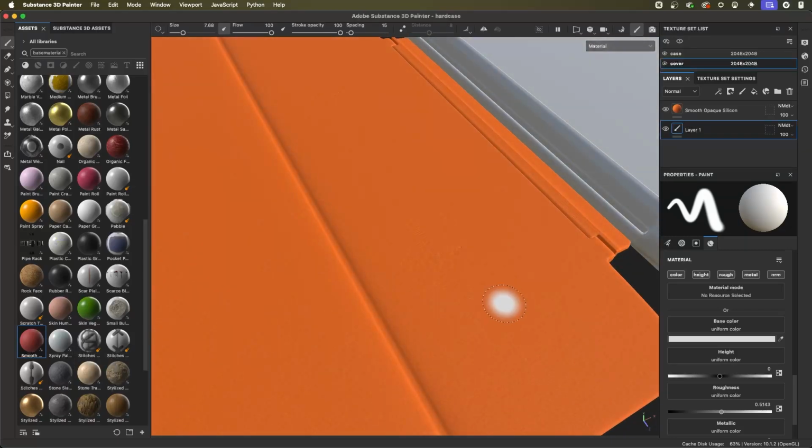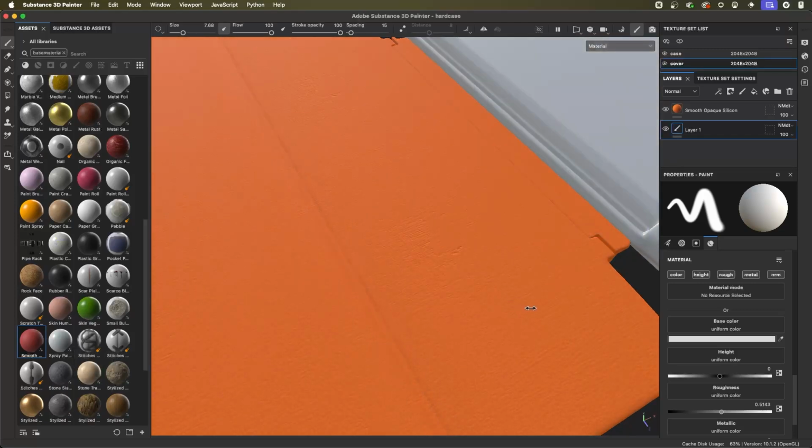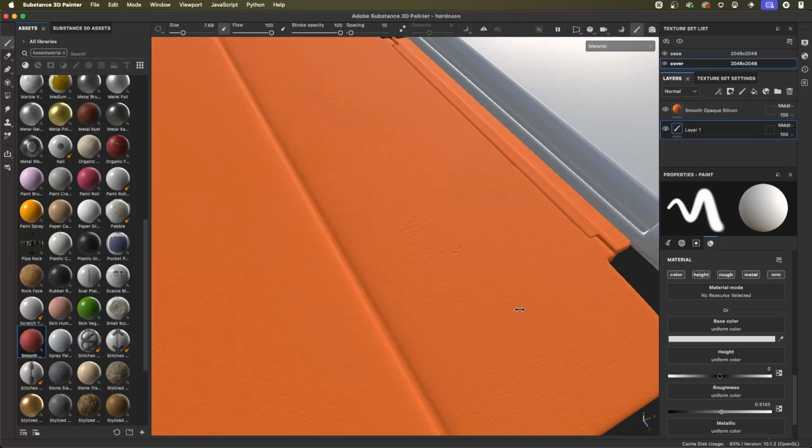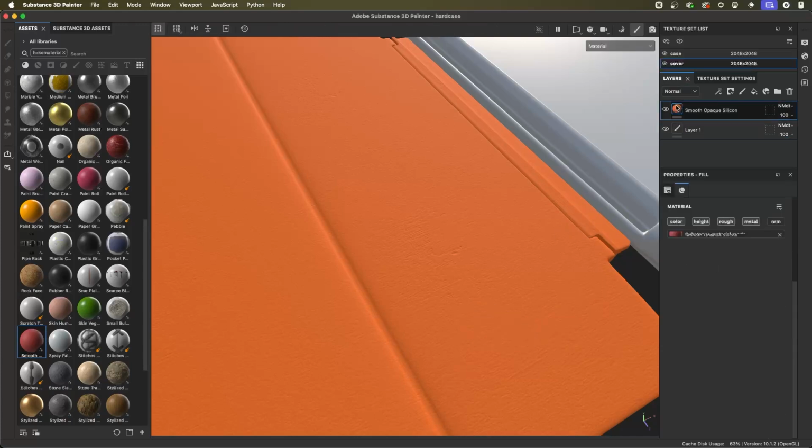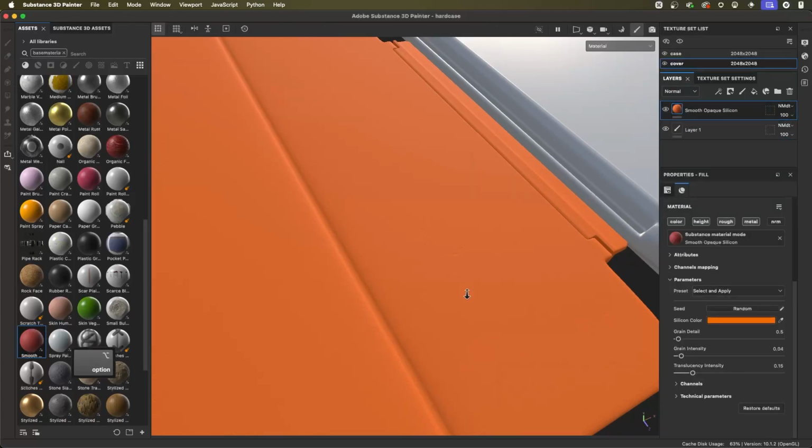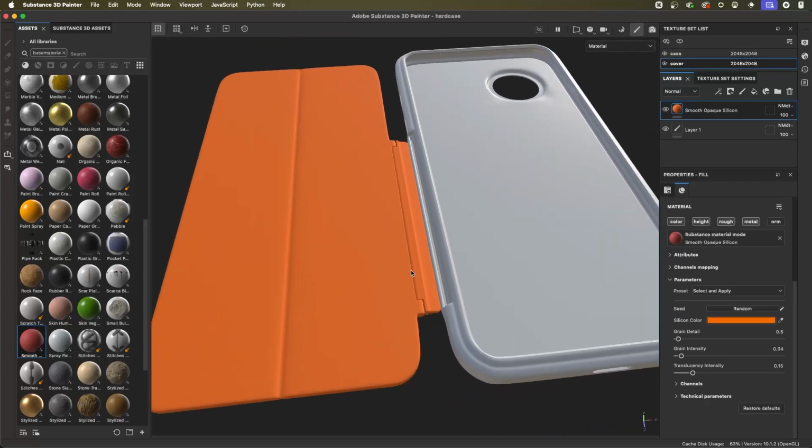So usually you'll do a tweak to your material, you'll hit Shift, right mouse button, move it around, and get a good feel for how the lighting is interacting with the surface, or more accurately said, how the material is interacting with the light. And that'll help you gauge things like, what do I set for this intensity value? You know what, I will just drop that grain intensity down a little bit.